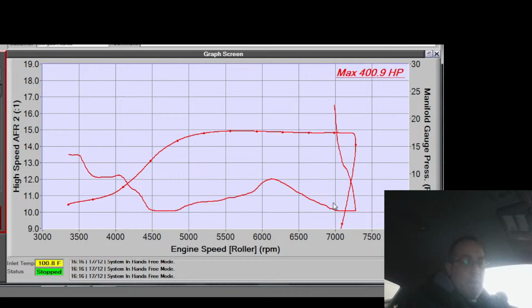If you look at two spark plugs with two different heat ranges, you can tell which one's the hotter plug, because the ceramic connects to the body of the plug much further away from the electrode on a hotter plug than on a colder plug. I've had plugs so cold the ceramic is about this long before it connects to the body of the plug. And on higher heat range plugs, the ceramic is like this long. What we're doing is hanging this piece of metal out in space, supporting it with ceramic, non-conductive material, and letting it get hot.